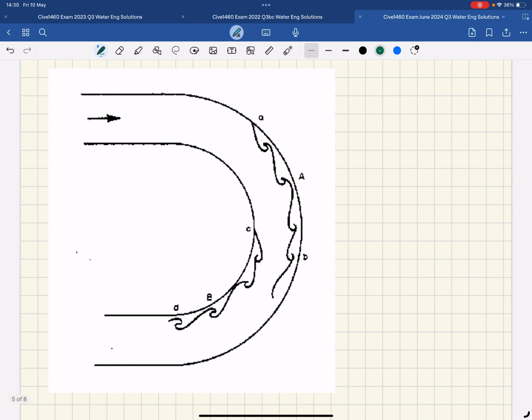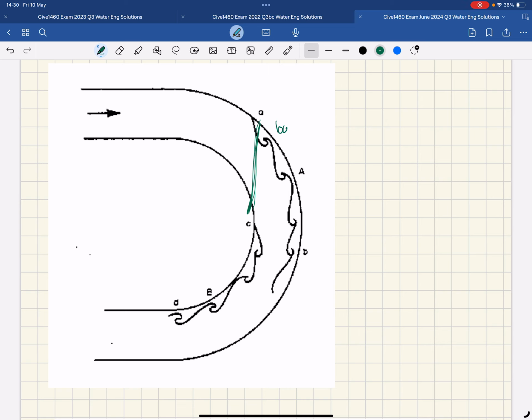A very sharp bend, like this U bend, again you've got an increase in the flow area here. Where you've got an increase in the flow area, you get reduction, lower U, higher P. So you got this flow there, and the same on this exiting bend.